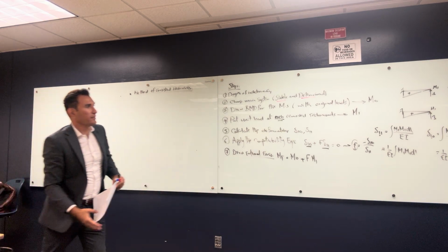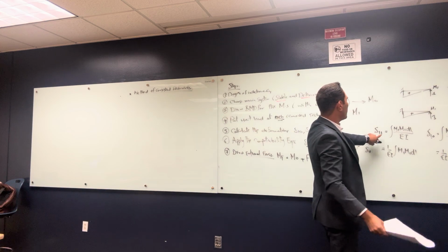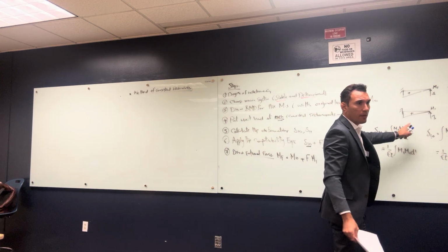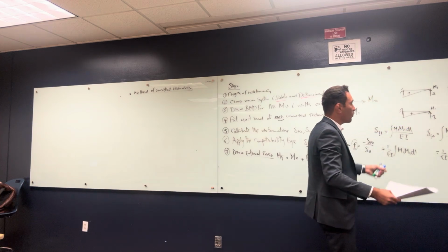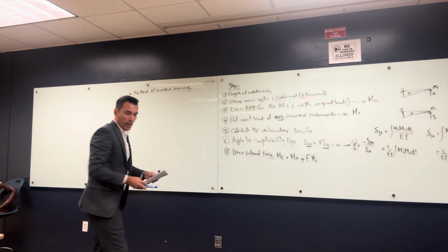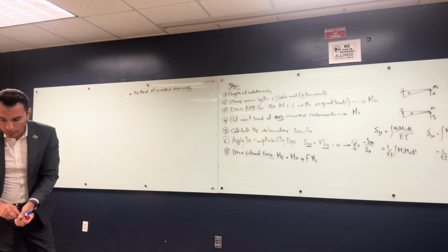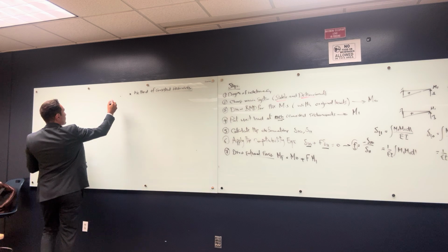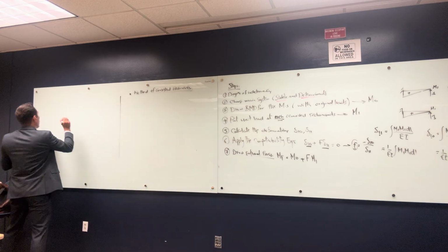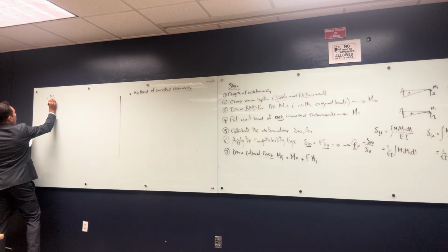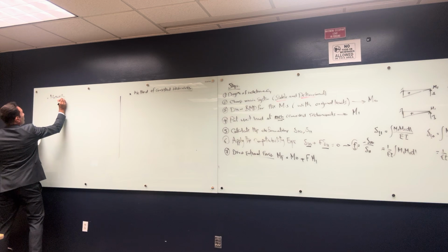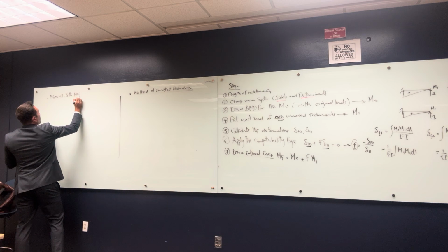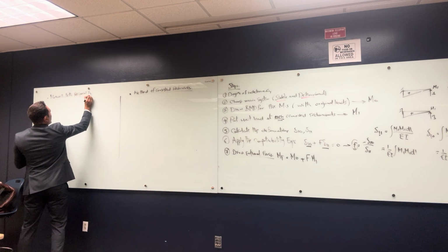Well, that actually makes sense. Here, if you are integrating delta 1,2, you are integrating M1 times M2. M2 times M1 is not going to make a difference because you just swap the equation. But this is actually a theory, and you will find it in the textbook. It's called the Maxwell-Betti reciprocal theory.